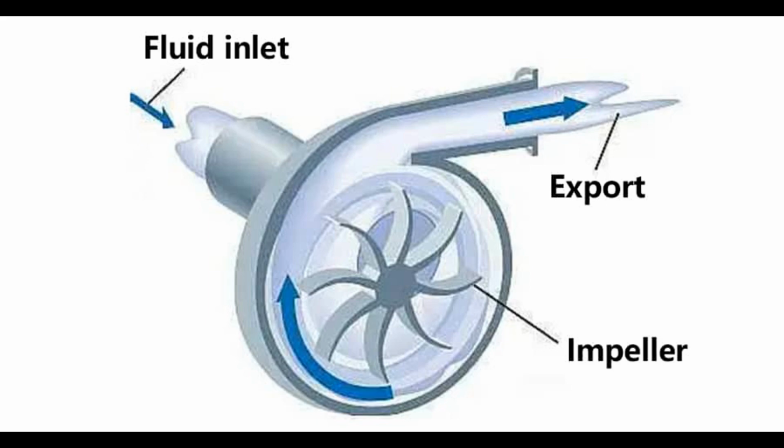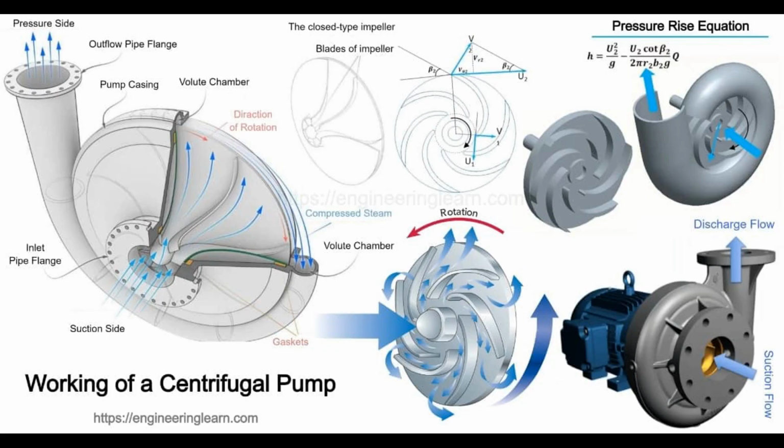As the impeller rotates, it imparts centrifugal force to the fluid, causing the fluid to move along the axis of rotation, away from the pump center. Low head, high flow. Axial flow centrifugal pumps are designed for applications where a high flow rate is required, but the head pressure is relatively low. They are particularly efficient in moving large volumes of fluid with relatively low lift or head.